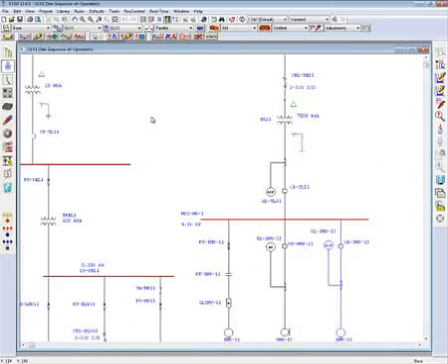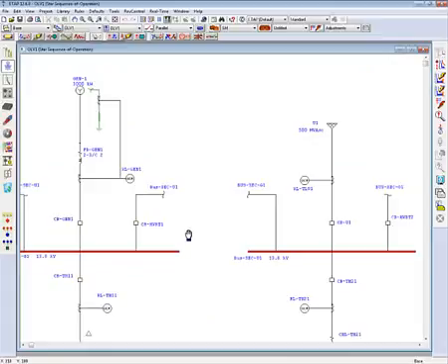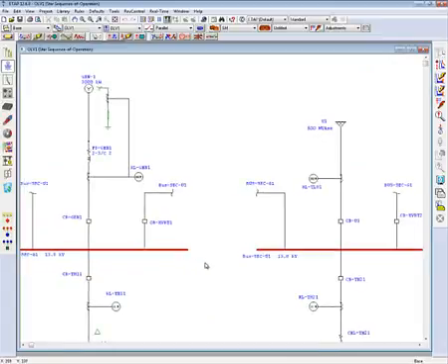If I take you back to the top or upstream of the system, you can see that the generator and utility are connected through a main breaker and some tie breakers between them. Based on the status or service of these main and tie breakers, we can have either one single source of contribution or multiple sources of contribution. So let's see. I have set up some configurations here. I have configuration local, parallel or utility.